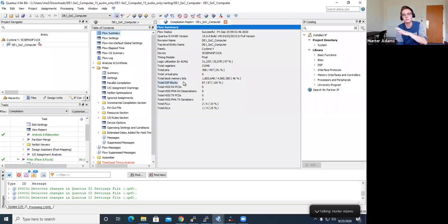You're doing all the physics simulations in Verilog, and you're manipulating the audio output with a busmaster in Verilog. So the HPS is really just telling it to go, maybe setting some parameters, but that's it. So this is almost entirely a Verilog lab, in contrast to the first one, which had a lot of interaction between HPS and FPGA.